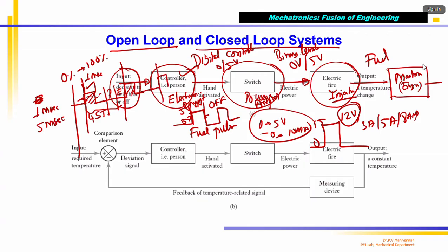So this is engine cycle. Every time in the suction stroke, inject the fuel. Okay, I'm injecting for 1 millisecond. That develops, for example, a few Newton meter that is sufficient to overcome friction. Now, if I press the throttle, 20% throttle, I will open for, sorry, 2 milliseconds, for example. Fuel pulse will be 2 milliseconds.